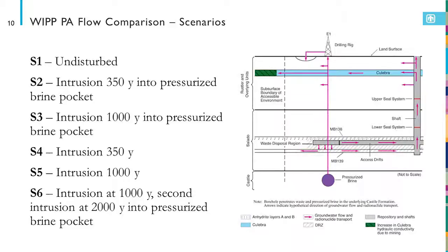So we're not going to talk about the codes that model the direct release at the time of borehole intrusion, but we are going to consider flow up the borehole when the borehole seals fail, and that could be a source of radionuclide transport to the Culebra and from there to the accessible environment. So that's just one possible picture.